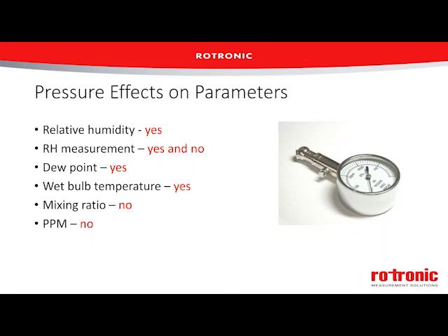And if we're using a capacitive sensor, those measure relative humidity directly, so they're already compensating for whatever the pressure is in that system. If though we are measuring dew point and calculating relative humidity, it's very critical that we know what the pressure of our system is. Otherwise, we will get an incorrect relative humidity measurement. So that's where pressure can become very important for us to understand and know within our system.